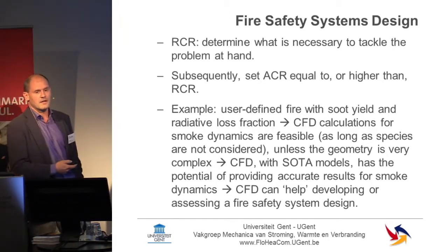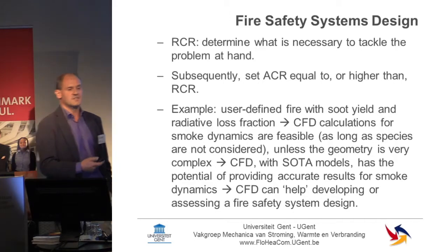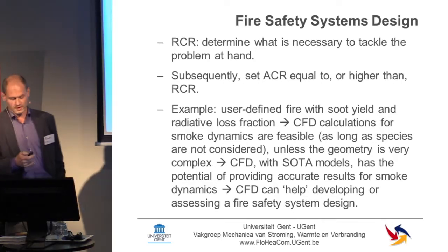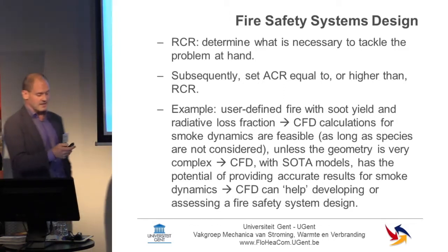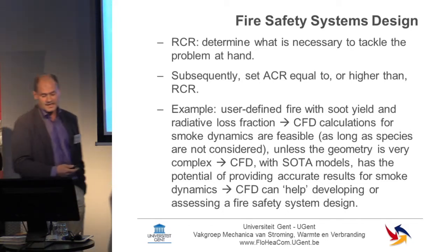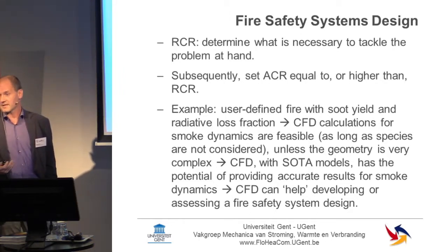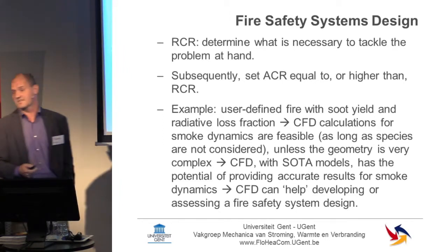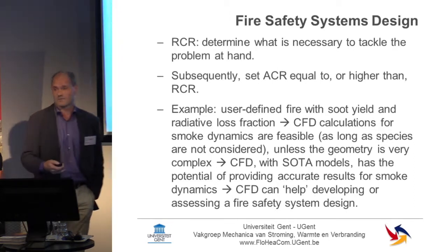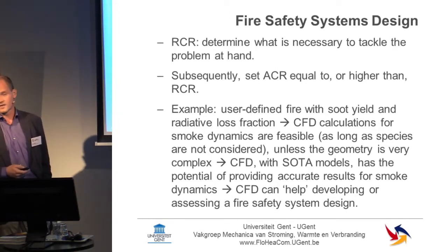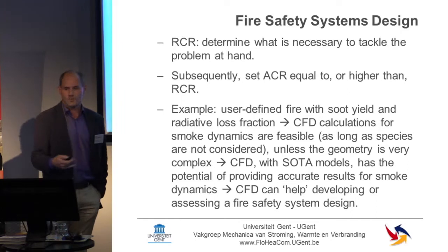fire safety systems design. If as a user you define a certain fire scenario and as a user you establish the production of soot relative to the radiative loss fraction, you see that the CFD calculations at this point in time for smoke dynamics are very feasible, very reliable as well. That is, as long as we don't touch the subject of toxicity, because toxicity continues to be a very difficult problem to solve, particularly the production of carbon monoxide. It's not a problem that is easy to solve.